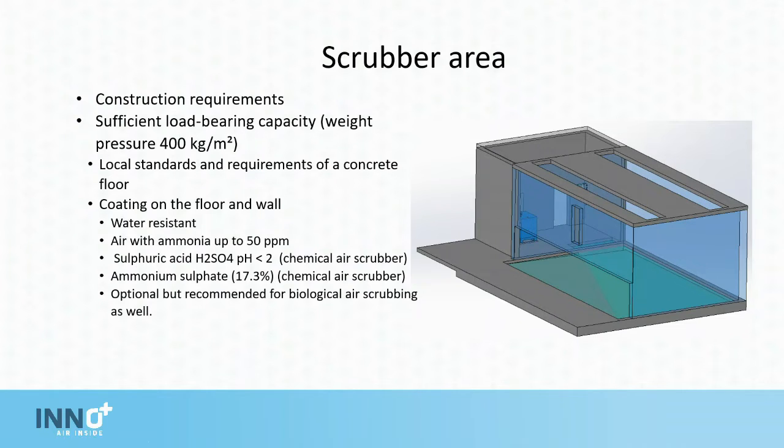Also, when using a chemical air scrubber, it should be resistant to ammonium sulfate. When using a biological scrubber, it's strongly recommended that you use this coating as well.